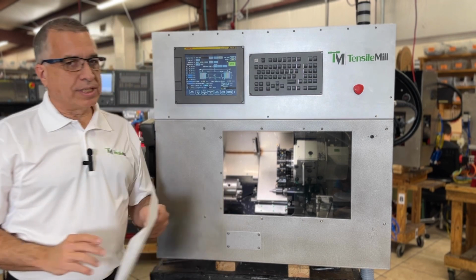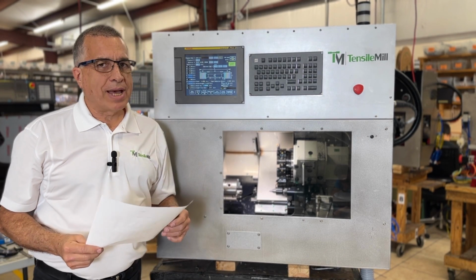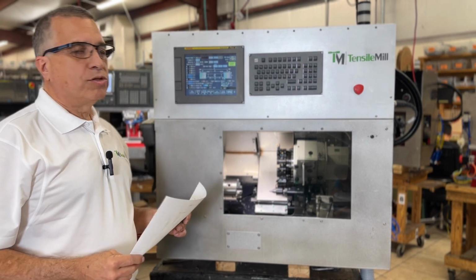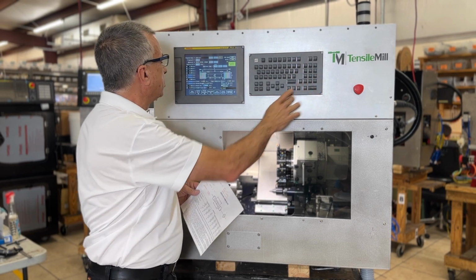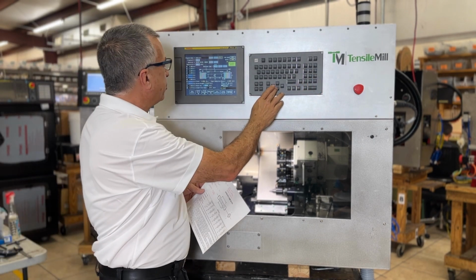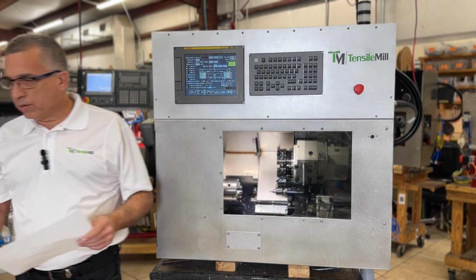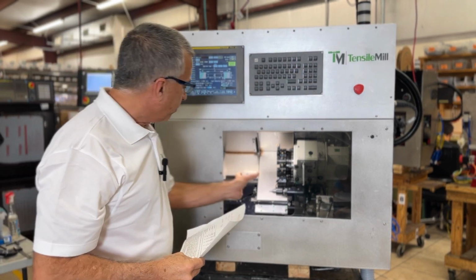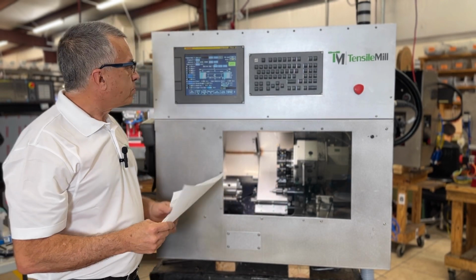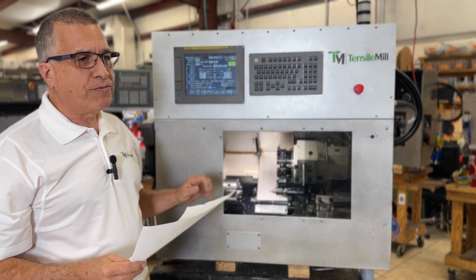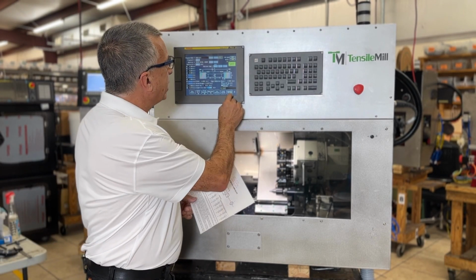The stock diameter, this is very important so that the program knows how many passes it has to make in order to make the part. So 0.62. Length from jaws, the actual length, we can do that later. The length from the jaw is when we put the part here, we want to measure the length exactly. We won't worry about it too much now because first we're going to do the center drilling. Okay, then we can simulate the part.